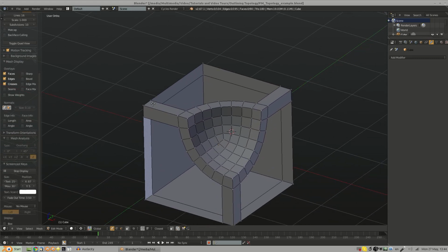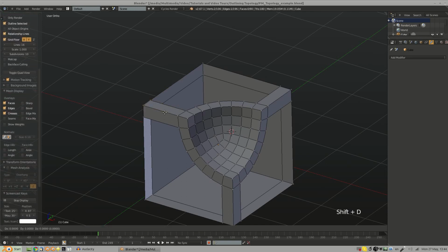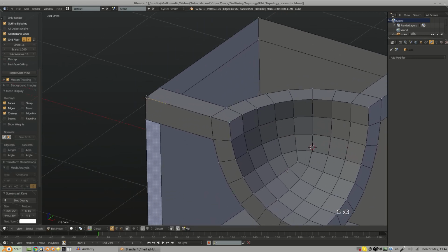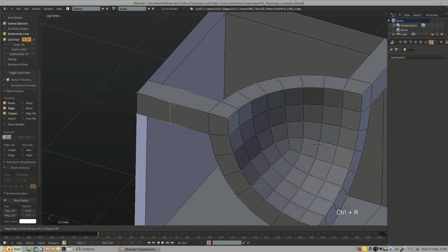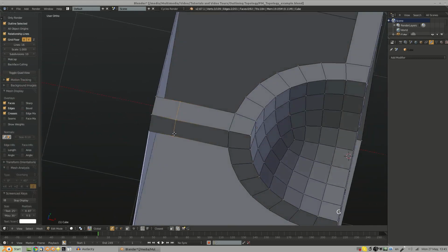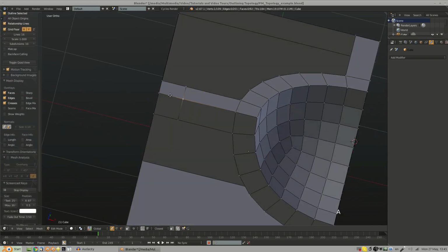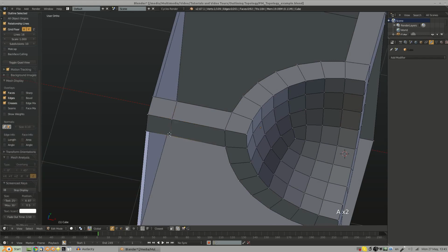So there's a few other things I want to make sure I get in here before I start filling this in. So I'll just take these vertices, duplicate them. Whoops, I'm still set to 3D cursor. So yeah, I just want to rotate these around the Z actually, and just snap them to there. There we go. Snap them to there, then add my edge loop, scale it in along the X just to make sure it's nice and flat, and that would be where's that other vertex?